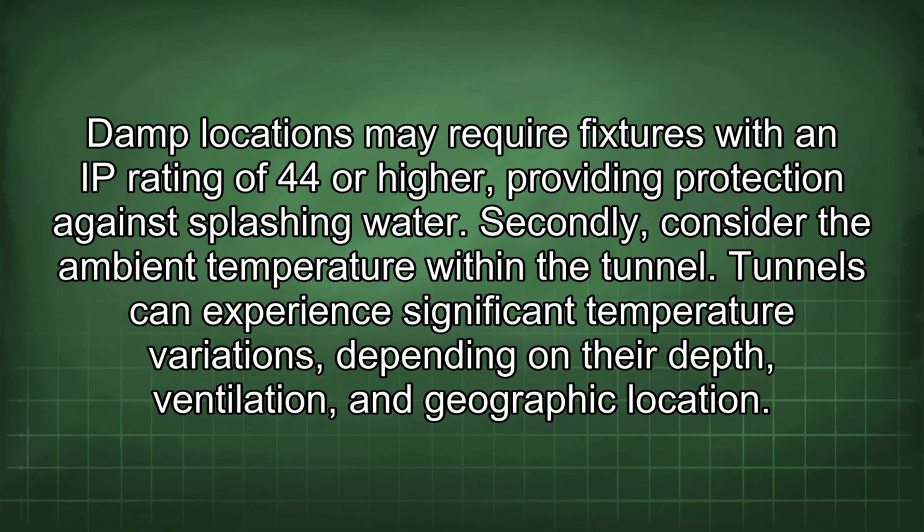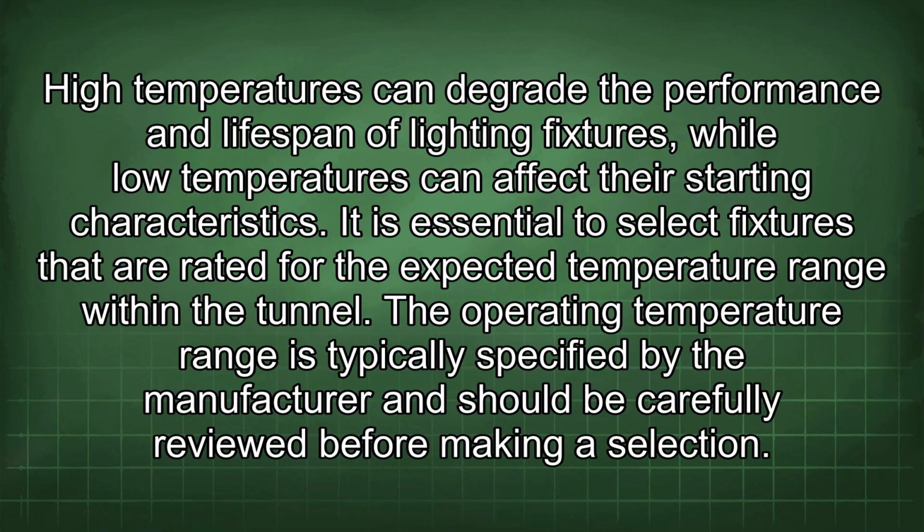Secondly, consider the ambient temperature within the tunnel. Tunnels can experience significant temperature variations depending on their depth, ventilation, and geographic location. High temperatures can degrade the performance and lifespan of lighting fixtures, while low temperatures can affect their starting characteristics. It is essential to select fixtures that are rated for the expected temperature range within the tunnel.